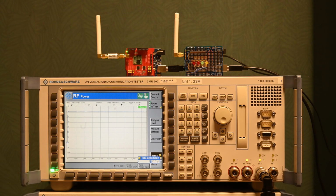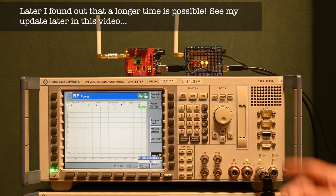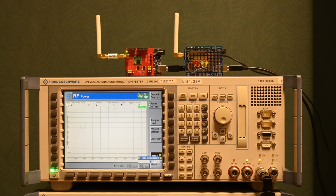Well, the actual setting here is that we cannot go beyond this 9,000 milliseconds, so 9 milliseconds. And I think that is per division on this unit. So the burst of this is fairly long, and I think the device, the CMU, has been designed for devices measuring stuff with much shorter burst time, like telecommunication protocol. But this LoRa thing is fairly slow. That's the way the radio protocol of LoRa was designed, for deep penetration, etc., but not necessarily for speed. So we cannot really look at that.